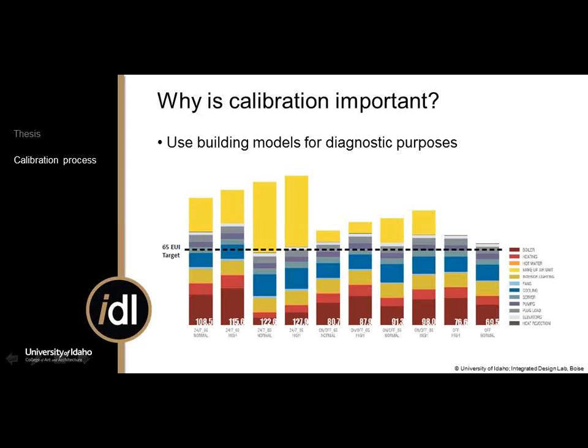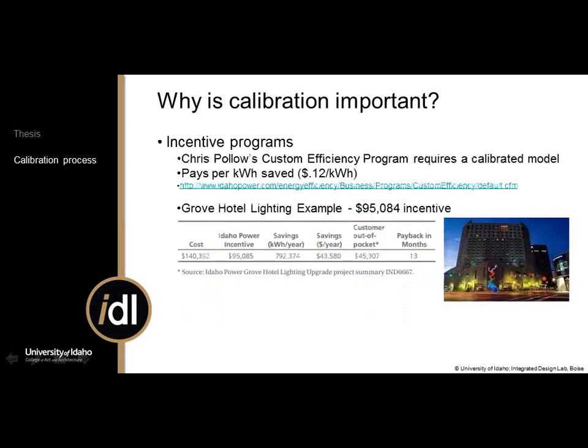And this yellow bar represents the variations between those different accounts that we got from interviewing the different people we were trying to get information from. And you can see that it has a huge difference on the overall target EUI that we're trying to calibrate. So through this and through some more investigative work, I believe we were able to arrive at this slice here, which was an on-off operation, only being operated during the daytime with a set point of 65, with normal infiltration layered onto that as well. So you can see that that's one of the processes that we can use to help diagnose buildings.